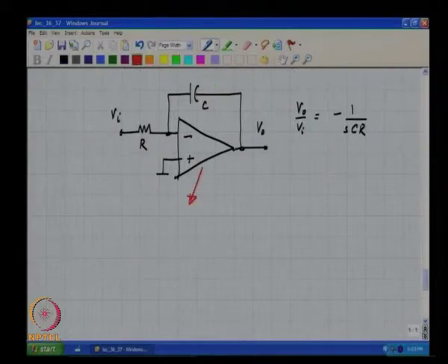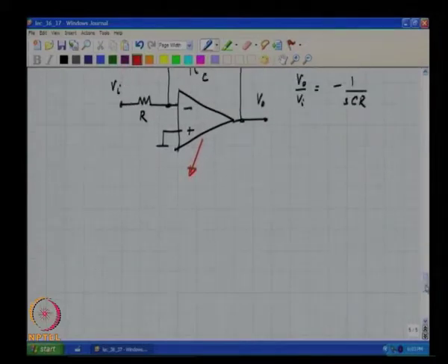One way of realizing the op amp is to think of it as a voltage controlled voltage source with a very large gain A. Unfortunately, in CMOS technology, if you try to realize an op amp as a voltage controlled voltage source, the signal swing that the op amp can support at its output is severely constrained.